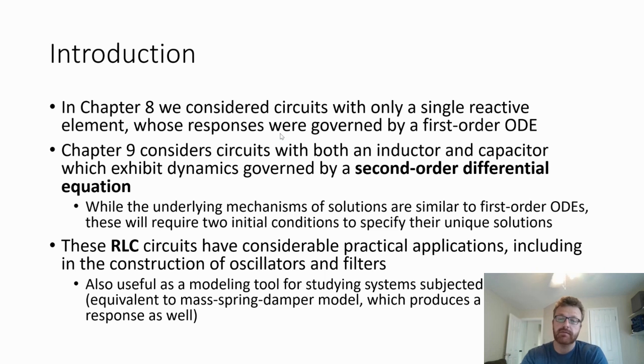Now, first order just means that those differential equations, the highest derivative term that we saw in them was a first derivative. And don't worry too much about what ordinary differential equation means. That's just in contrast to a partial differential equation where the functions that satisfy the equation have more than one variable. So a lot of terms there, but basically what we saw is that if you enforced Kirchhoff's current law or Kirchhoff's voltage law, you got an expression that related either the current or the voltage, namely its derivative, to itself. And what we found is that when we guessed that the solution would be an actual exponential function based upon our knowledge of how exponential functions work, namely when you differentiate them, you get a scaled version of the function back themselves, that was in fact true.